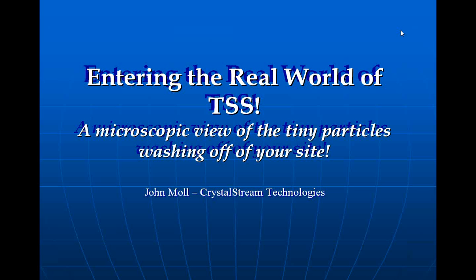I'm privileged to be able to look through a dissecting scope or a macroscope and try to analyze what we see. The common materials we find are the total sediment load. I've advocated that term because people say total suspended solids. If you read the definition in Management Measure 5, it says that that would be actual suspensions. It would be material that can be suspended up in the water column. Material that saltates. Saltation is the bouncing along the bottom of a bed by a particle that can't quite get airborne, but it is rolling or moving or creeping. Sometimes it does actually bounce.